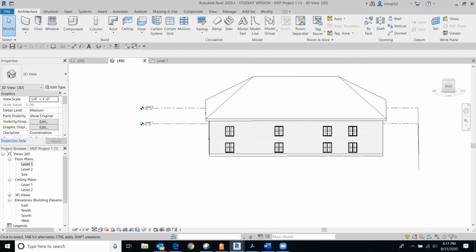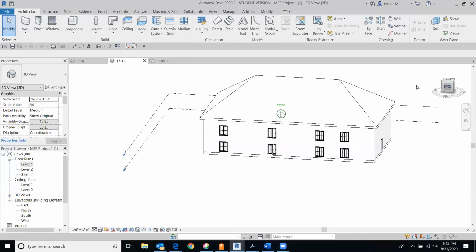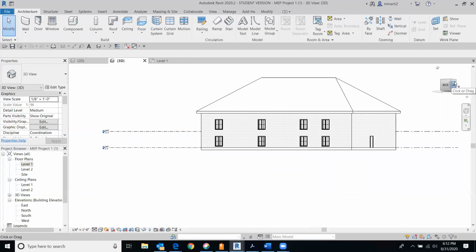Now, those of you who are familiar with the regular Revit, you'll notice that in my project browser, which is one of the main driving points of Revit, that is still an architectural template that we started with. We just have our floor plans, ceiling plans, and things like that. So the gist of MEP is we always are going to be starting with an architectural template.